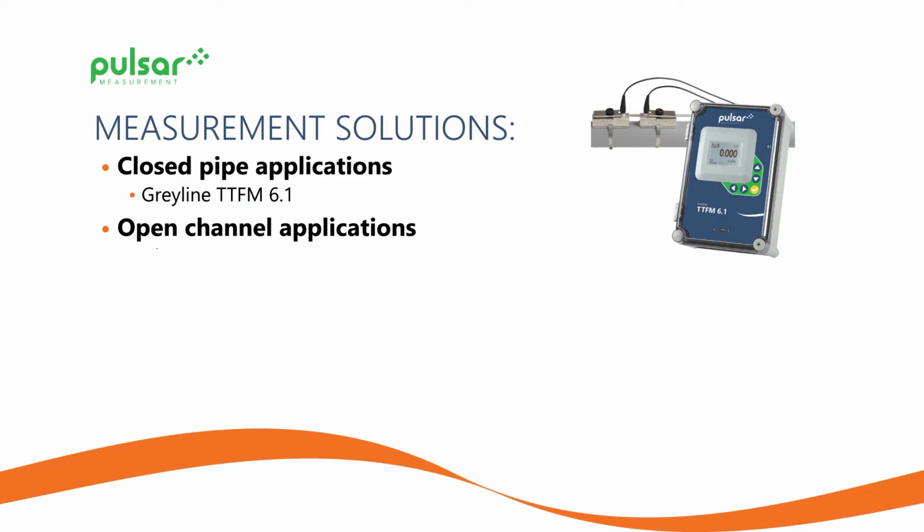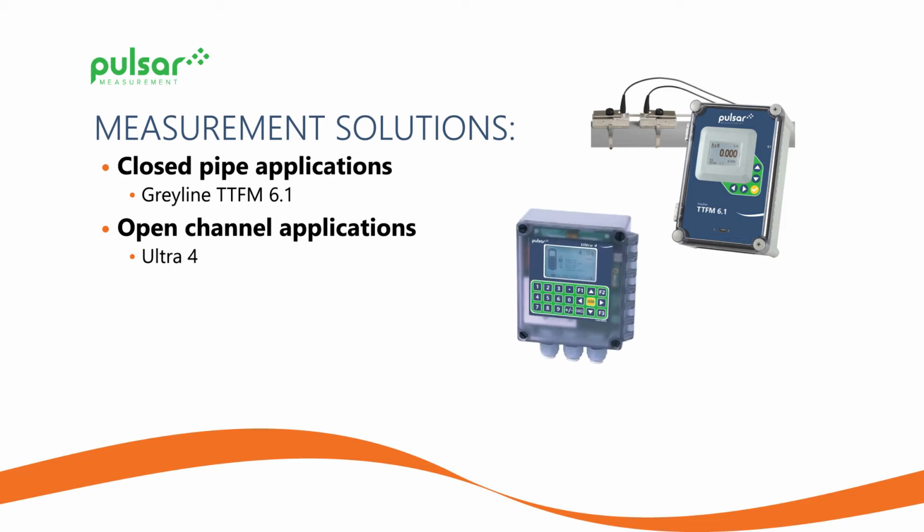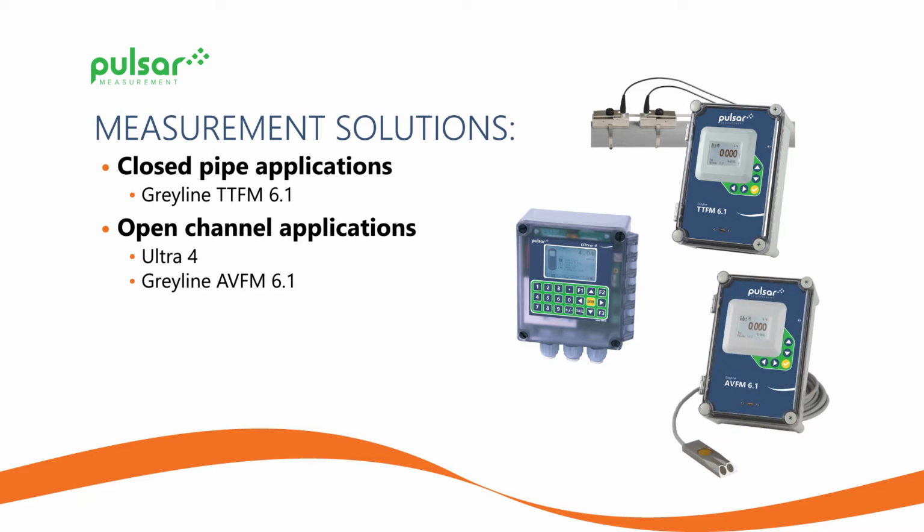For an open channel solution, we have two methods. We can use our top-down ultrasonic, our Ultra 4, which is very simple to use, also has onboard data logging and trending so you can see previous abstraction limits. And for non-standard applications, we have our AVFM, which can feature both a velocity and a level measurement system in the same device, which then can be recalibrated to give you a flow measurement.